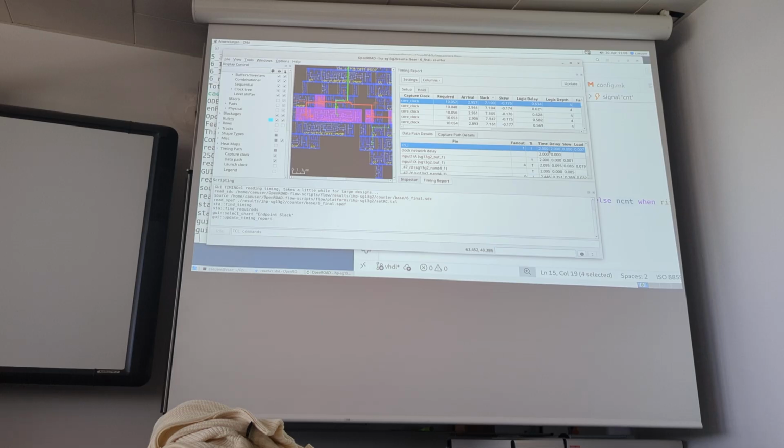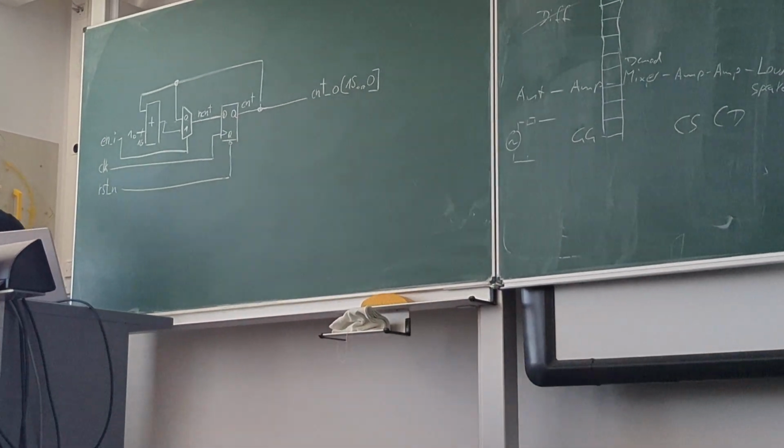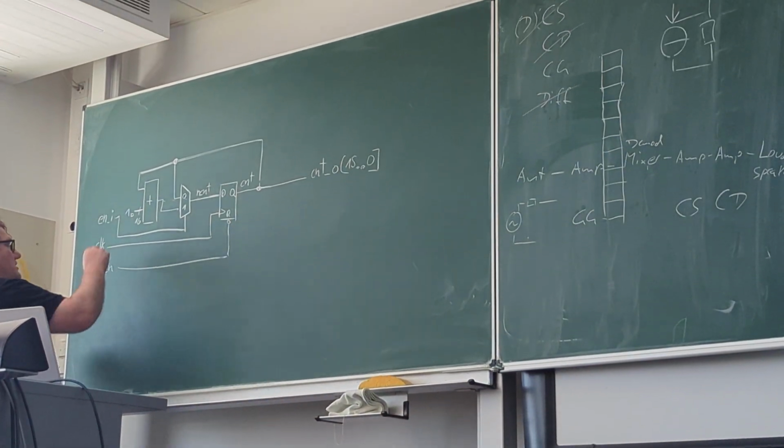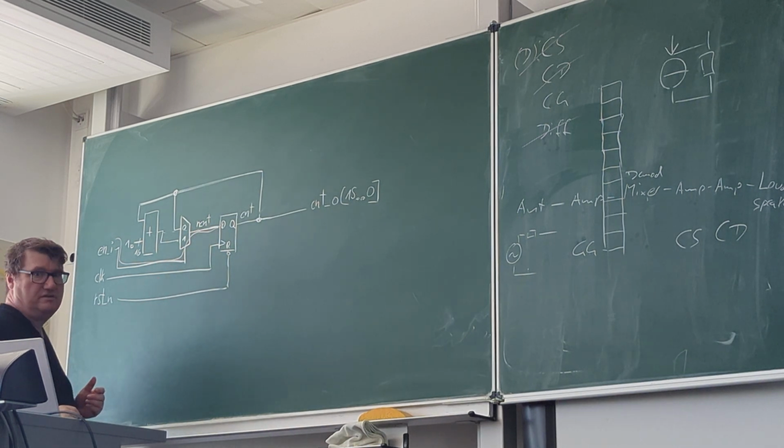So we said it will be clocked with our 50 megahertz clock. That's the core clock. But it starts at the enable input, so there is no real register where it starts at the primary input. So we have a critical path that somehow goes through the enable input and ends up here.